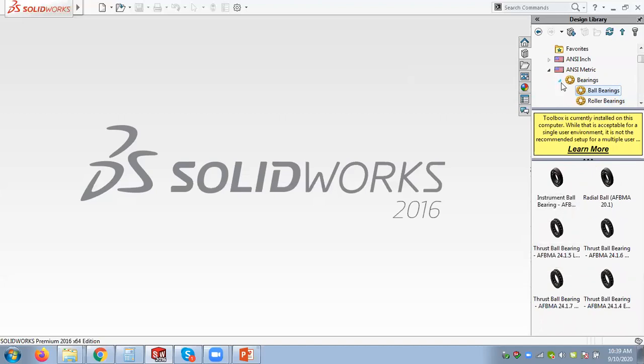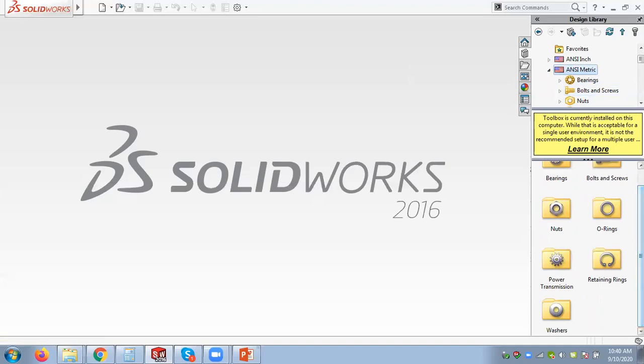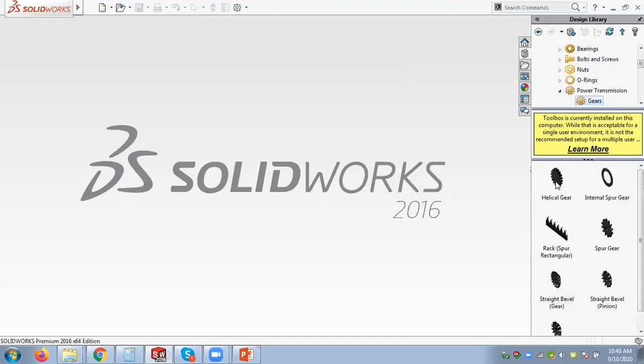Last year in the exam we also asked you to use these design libraries. You can draw your gears or you can use the libraries and complete your work. I can go to power transmission, and here you can go to gears. You will find a set of gears here.